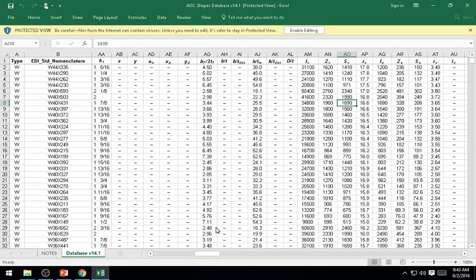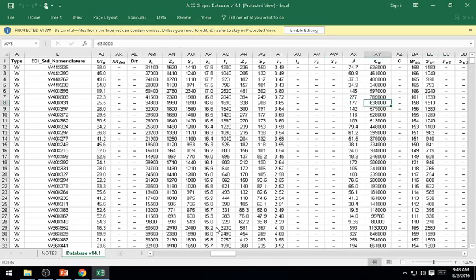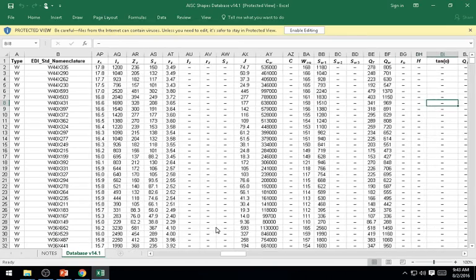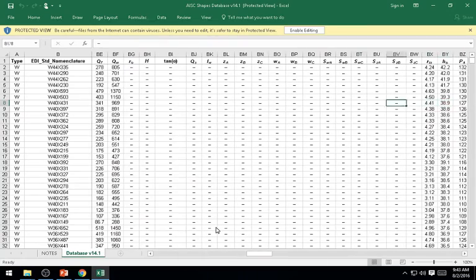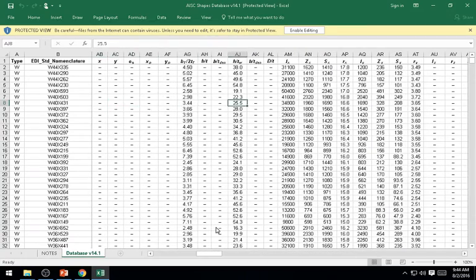Among other properties, they have what we just learned about today, the S. So really, if I wanted to, back up. They also have Z, which is the plastic section modulus. Hey, look, the polar moment of inertia, and all sorts of fun properties that you can go on and on for days. But usually you don't need to use all of these when designing. For our sake, we're mainly going to be concerned with, and hey look, radius of gyration.